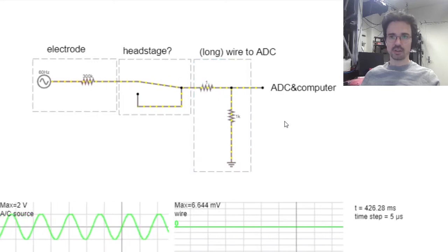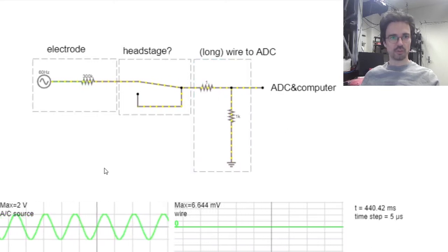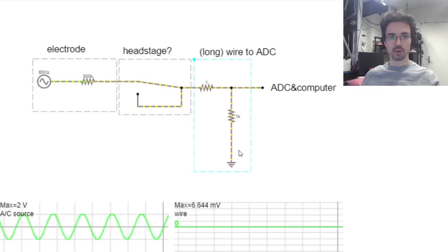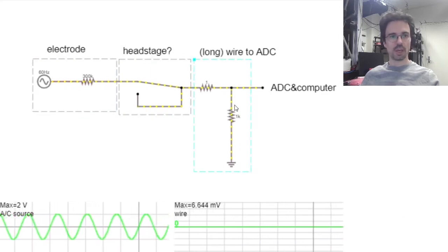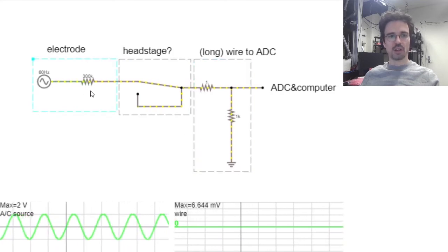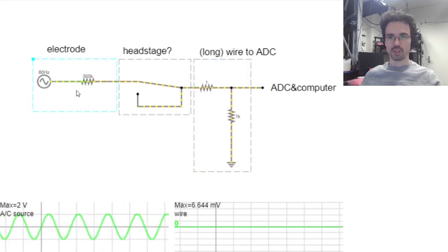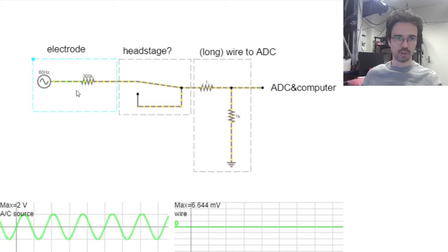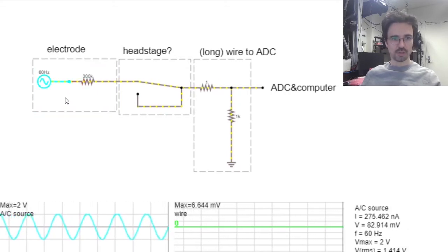And in the simulator, it's very nice. You can see what the current is doing. First of all, you can see that there's a decent amount of current flow down here to ground, because we have a large voltage drop across this resistor here. That's just straight up Ohm's law. And you can see on the left side here, we have 2 volts.